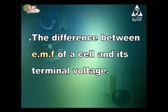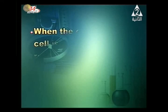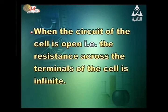When does the difference between the EMF of a cell and its terminal voltage equal 0? Actually, the problem asks for when the difference between them is 0. This happens when the circuit of the cell is open. That's to say, the resistance across the terminals of the cell is infinite.